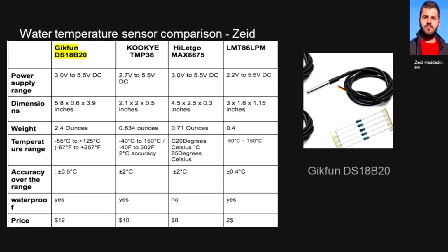Water temperature sensor. The DS18B20 temperature sensor is among the greatest water temperature sensors compatible with the Arduino. It is a very precise digital temperature sensor that works with most microcontrollers and electronic devices because of its wide working voltage range. Also, because of its waterproofness, it may be used in submerged areas. The one-wire protocol of the DS18B20 temperature sensor makes it simple to link it with the Arduino Uno Wi-Fi Rev 2 and include it in our project.